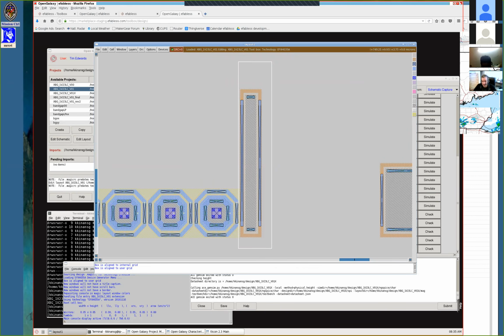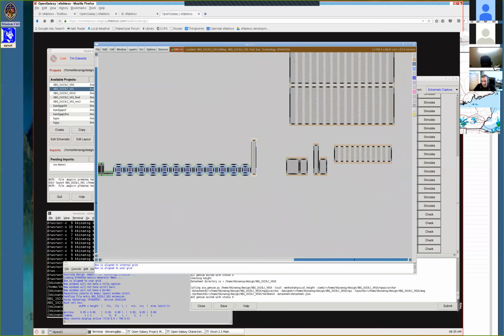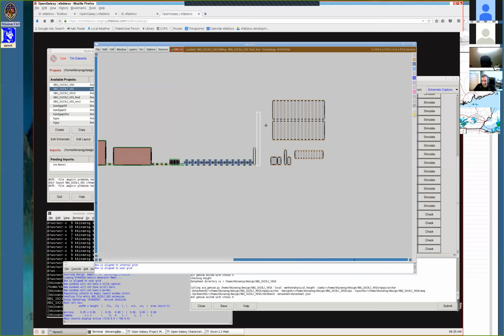The actual resistor is this layer right here. And you can tell that the whole cell is actually about twice or more the area of just the resistor. So when you get that area of the single device, you're getting something that's somewhat pessimistic for total area once you have optimized it, not just for the aspect ratio of the device or the compactness of the resistors, you've also reduced the total area of the devices.